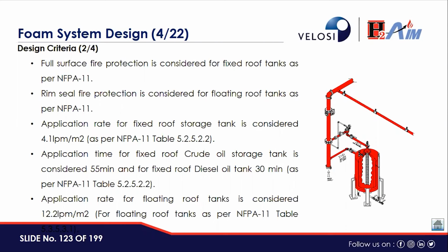Application rate for fixed roof storage tanks is considered 4.1 liter per minute per meter square as per NFPA 11 table 5.2.5.2.2. Application time for fixed roof crude storage tank is considered 55 minutes, and for fixed roof diesel oil tank it is considered as 30 minutes.